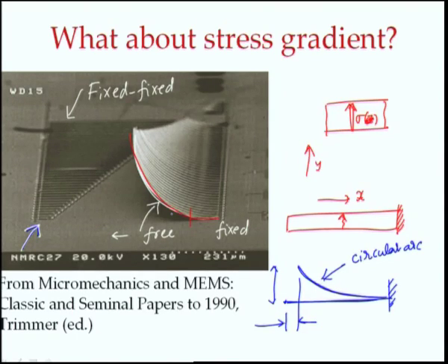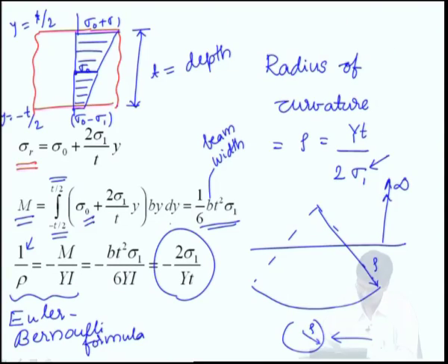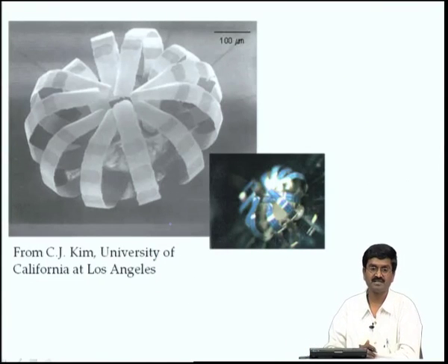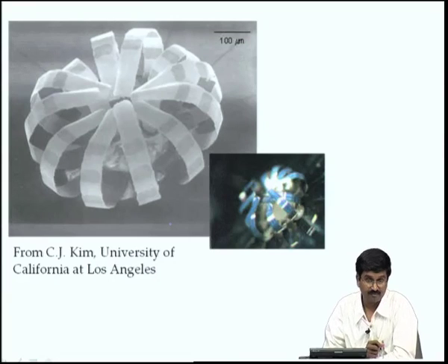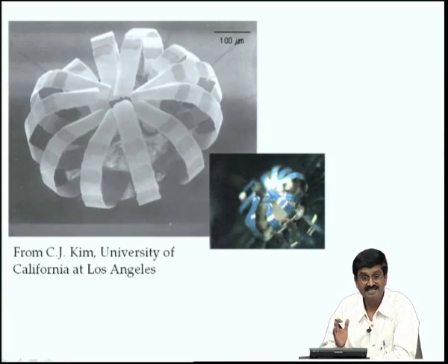So, just add a cantilever into your layout of the micro machine structures, based on whether it curves or not. If it does not curve, one can be happy that there is no residual stress in that process that you have done, otherwise by measuring it you can account for it. There are other uses, because if you do not account for residual stress, your calculations will be off, because residual stress does change the stiffness of an elastic structure.